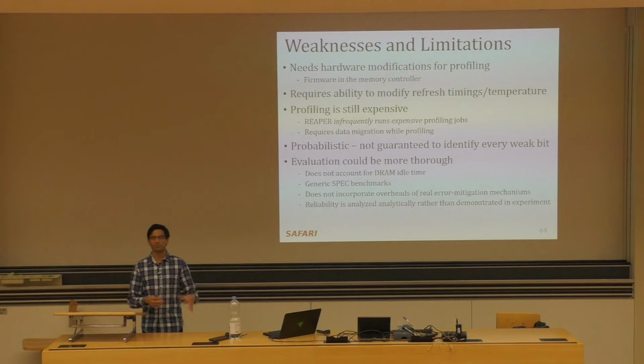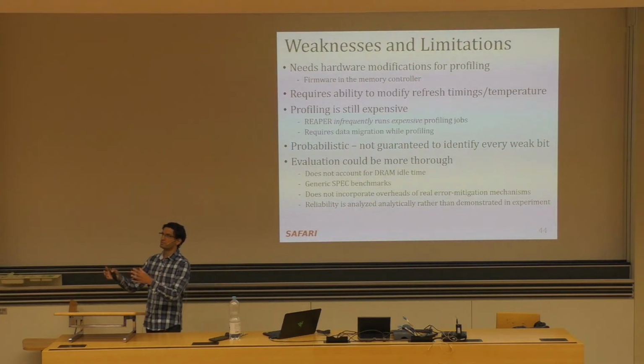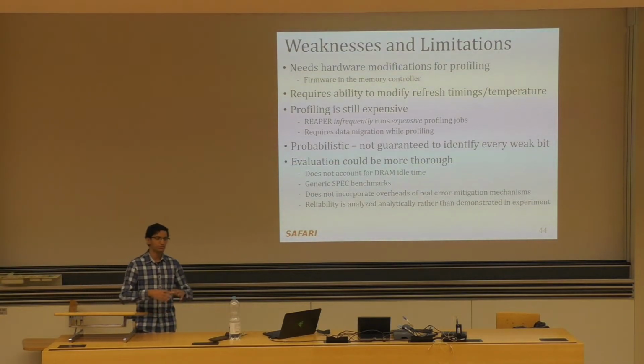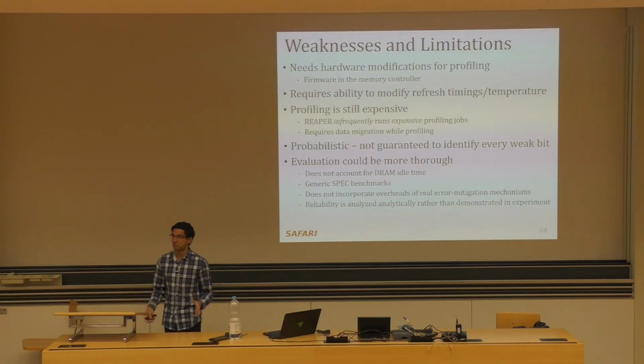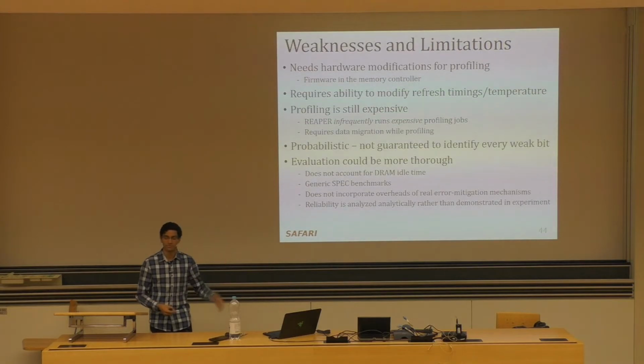Right, so for example, if we go back to that radar example I gave, we're refreshing different regions of DRAM with different refresh rates, right? There's some cost to that. We have to do some lookup to see what should be the right refresh interval for this region of DRAM, and I have to do some sort of analysis to figure out which regions of DRAM fall where. All of this comes at additional overhead, and that overhead is not encoded in this performance analysis that we did here.